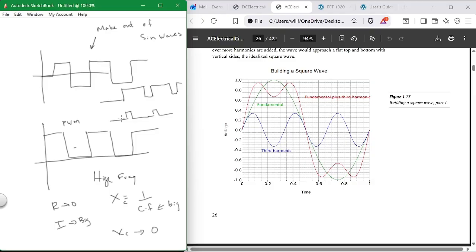So they would bring in the generators and put this tester on them, and analyze to see if these high frequency signals, not the low frequency ones, start to grow. If they start to grow, you've got a problem, okay?